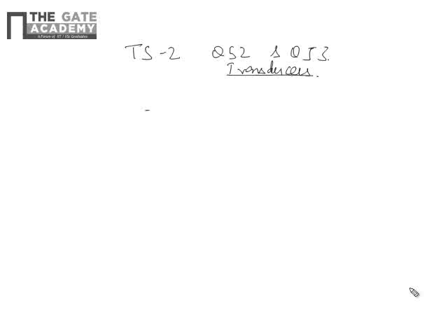Now here there are certain things to be assumed and taken care of. So if you see the figure carefully, then the area of the tube at section 1 and the area of the tube at section 2 is different. So for that we have to apply the continuity equation. So first of all, continuity equation. What the continuity equation says is V1A1 is equal to V2A2. So this is the continuity equation.